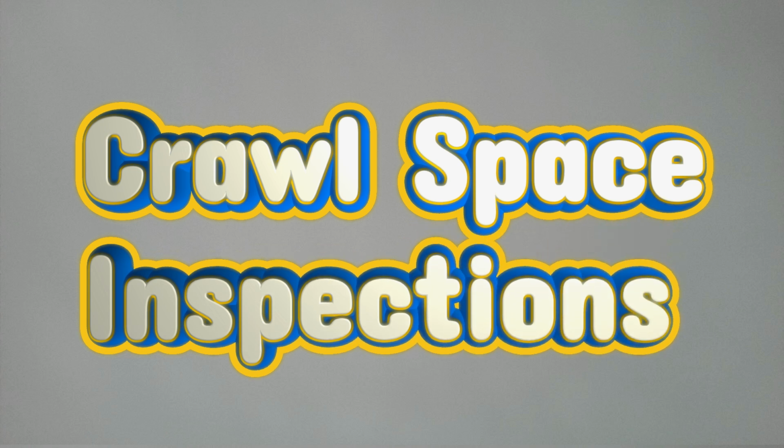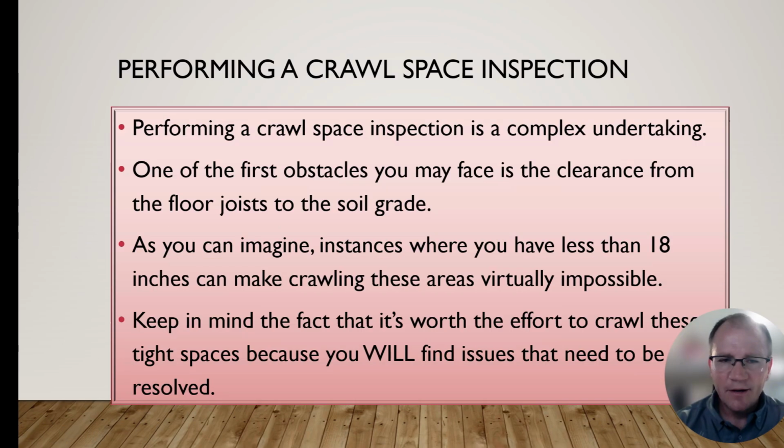Let's talk about crawl space inspections. Remember, performing a crawl space inspection is a complex undertaking. One of the first obstacles you may face is the clearance from the floor joist to the soil grade. As you can imagine, instances where you have less than 18 inches can make crawling these areas virtually impossible. Keep in mind the fact that it's worth all the effort to crawl the tight spaces because you will find issues that need to be resolved.